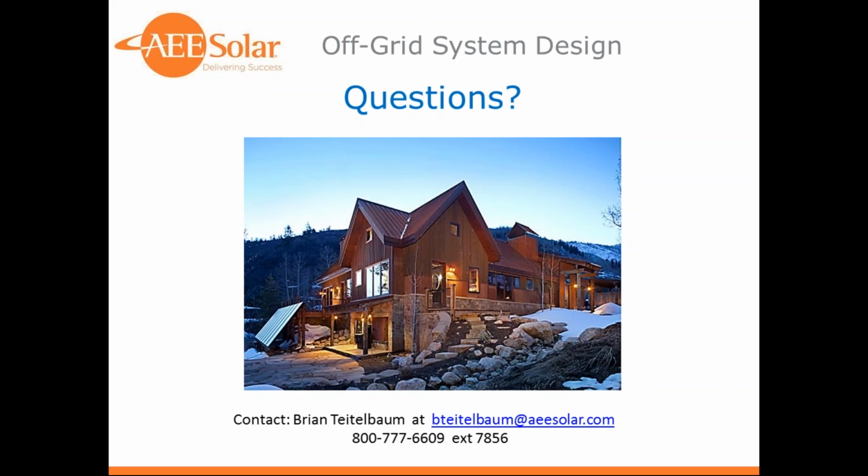Another good question. I do not suggest going over, and again, we're talking lead acid here. I do not suggest going over 3. 3 strings in parallel is really the maximum that you should design for as a design point. And even 3 strings is a little questionable. By far, the best application is a single string of cells.